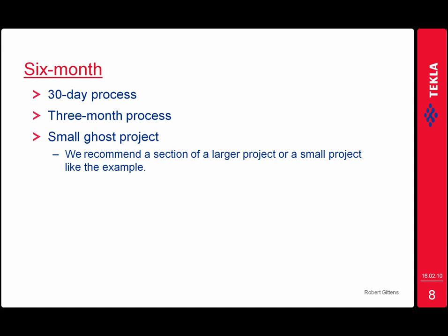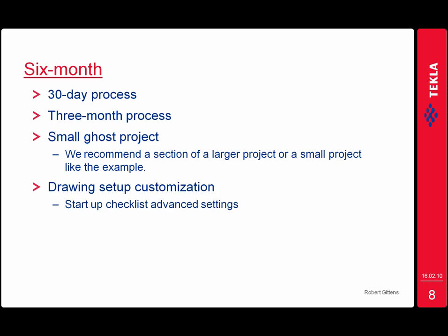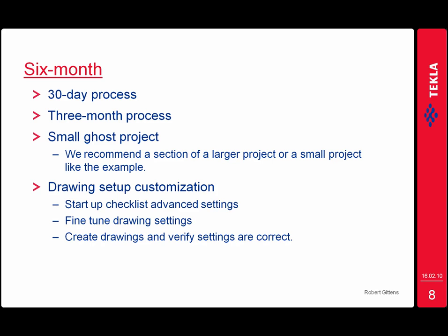We recommend doing ghost where you may have a parallel project going on that is a live project while you're doing the same project in Tekla, just to compare results and the different ways that can be done, just in case any other section symbols or anything need to be changed. Which brings me to drawing setup customization. You want to re-verify with your startup checklist advanced settings, fine-tune these drawing settings, create drawings, and verify the settings are correct.